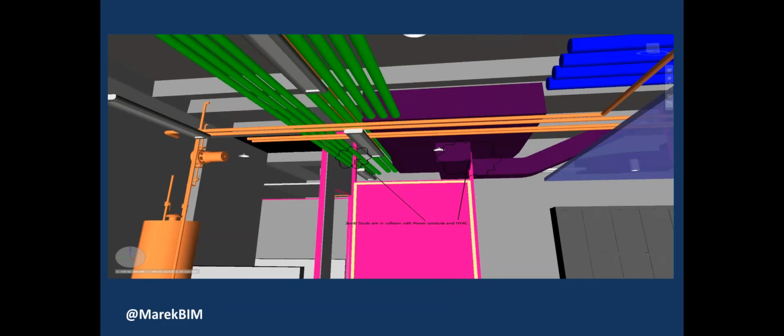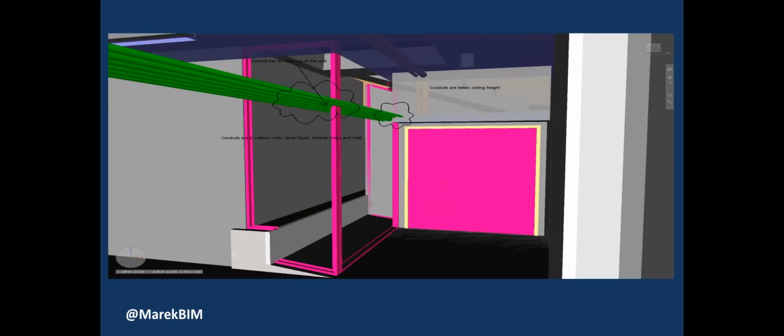And that's your pretty typical, what you run into is things that are usually pushed through door headers that it's a perfect place to shove mechanical stuff through, but they don't always take into account that the jam studs have to go to the deck, and we run into this a lot. It's a pretty easy fix in the field if we can identify it beforehand.